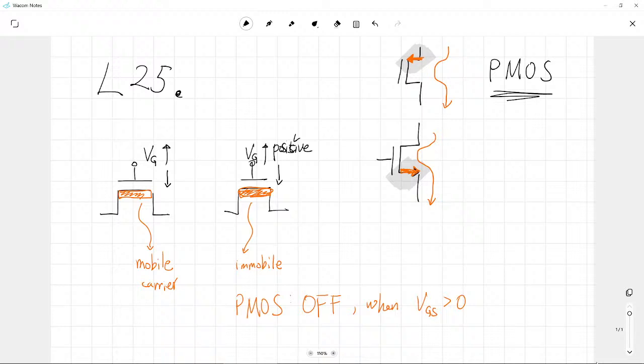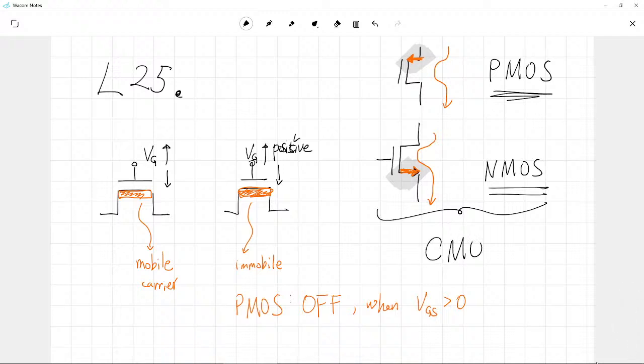But what I want to say is, in reality, in our semiconductor fabs, instead of fabricating only NMOSFET or PMOSFET, both NMOSFETs and PMOSFETs are fabricated at the same time. That's why, instead of NMOSFET or PMOSFET, we call it CMOS technology.